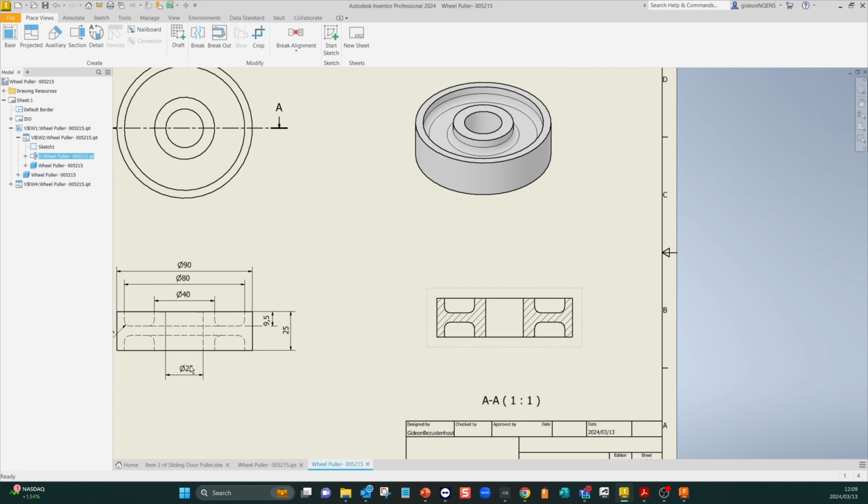So it's easy for them to manage and work off that. I'm just moving this up a little bit. The reason why is so that they can see the hidden lines, that would be an ID. If I move the dimension line down, you'll notice it almost looks like it's creating a solid line. I can edit that point and just bring it down.